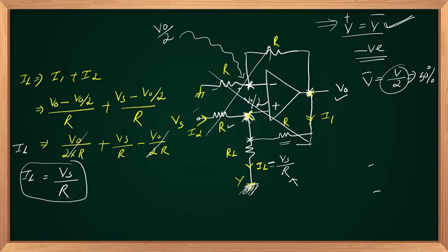So in any circuit in this configuration, if these cross products are matching, the current IL, you can directly write it as the voltage applied at the positive input side upon the resistance R, the resistance connected at the non-inverting input in series with the input DC source. Right? Let us evaluate the corresponding output voltage.